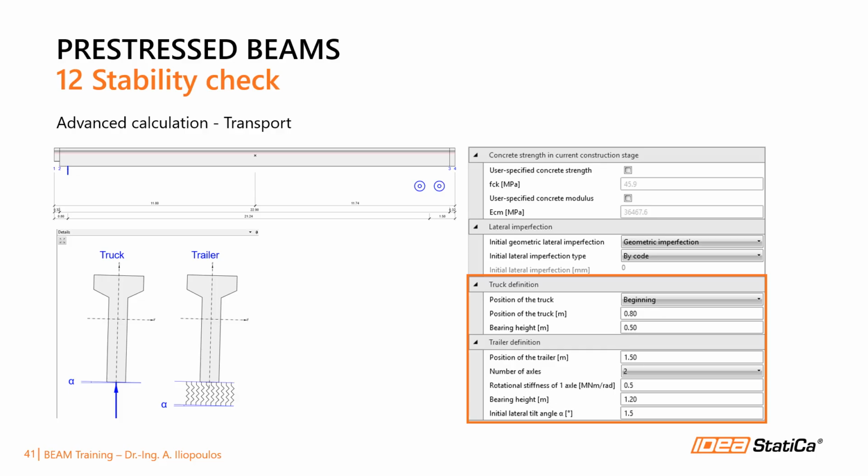It's in the range of 340 to 680 kilonewton meters per radian per dual tire axle. The higher values apply to rigs without leaf springs, in which the springing is primarily in the tires. For a single axle, half the value can be taken into account.